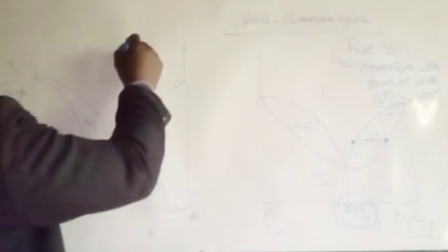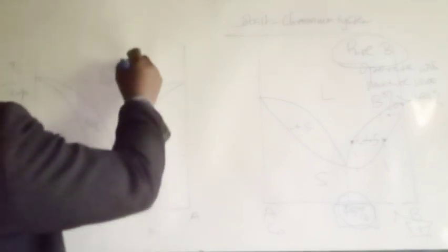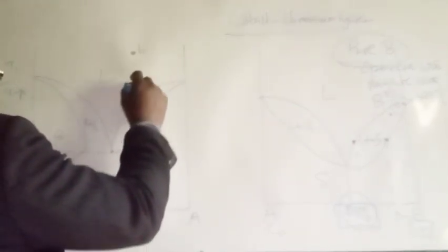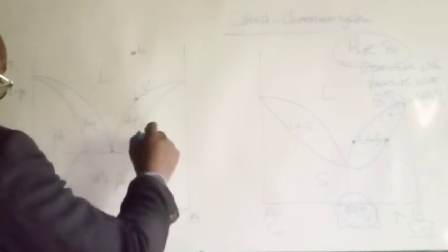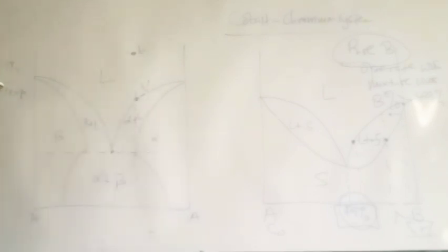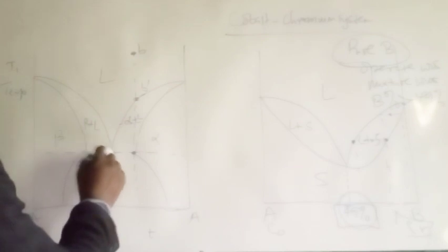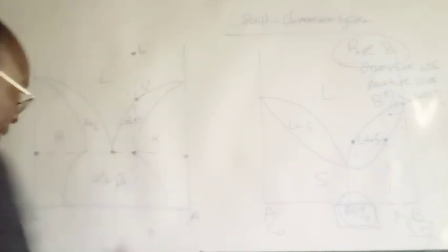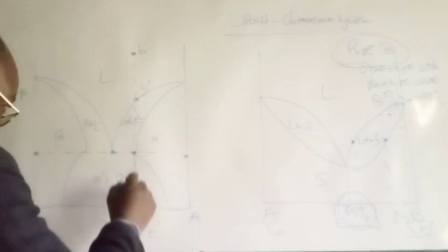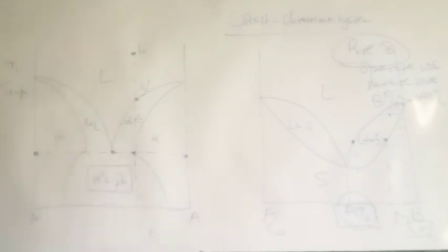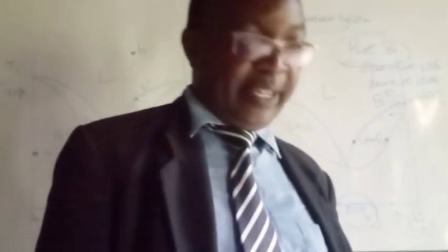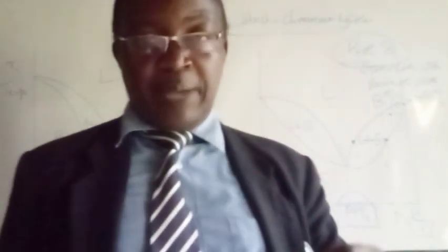And again, when we are dealing with this, just like we have already seen, we can get the behavior along an isopleth. So if you have B, when you use B prime, we are crystallizing out solid solution alpha from the liquid. The amounts continue, and when you reach this particular point here, we have the three phases coexisting in equilibrium, that mixture of A and B. So the system is invariant. Then when you look here, you are pulling the alpha and beta. So it's very straightforward in terms of interpretation.